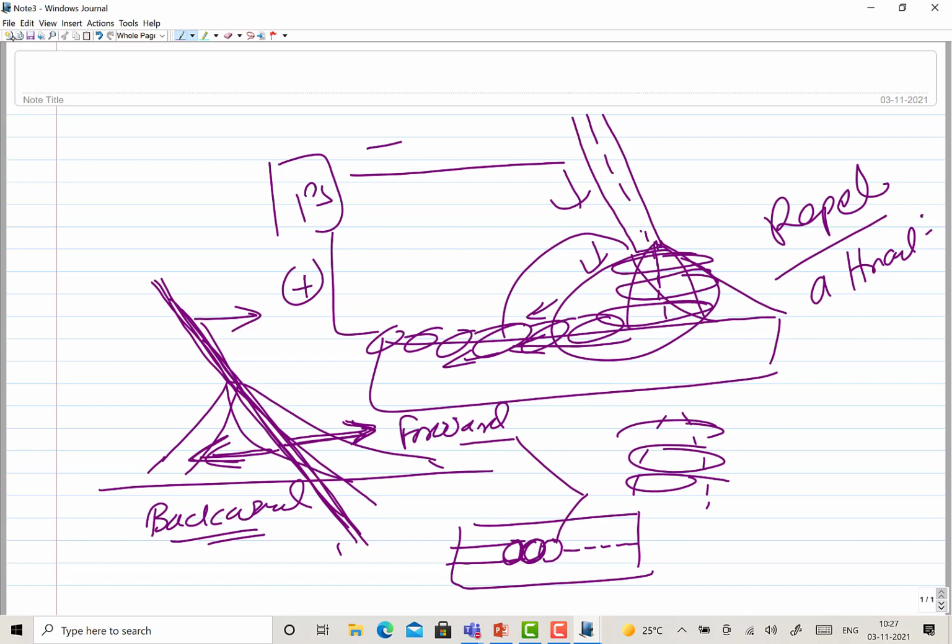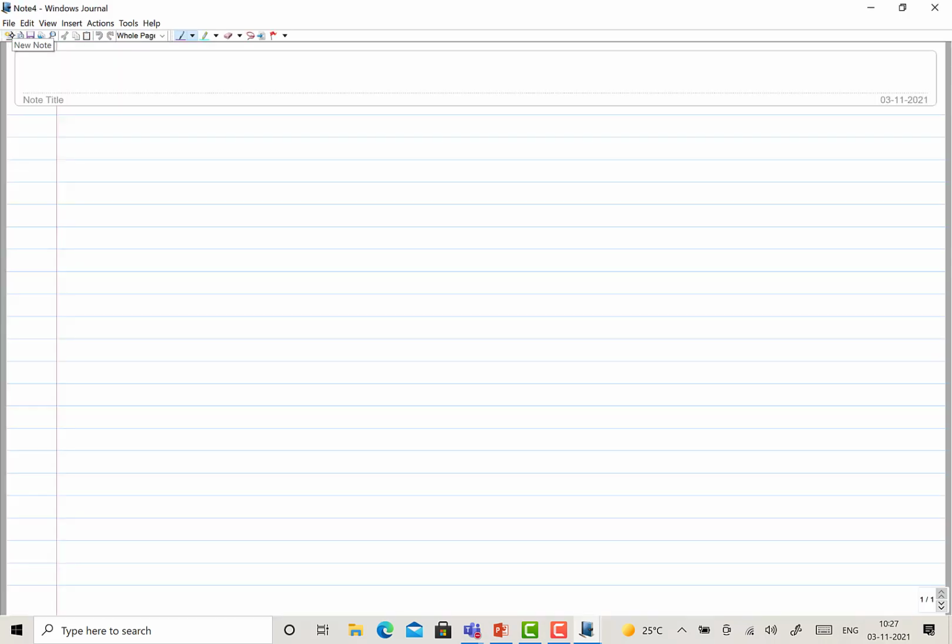The arc blow happens primarily due to the interaction of the electromagnetic fields generated by the flow of current through the arc and through the base metal. They can attract or repel depending upon the ground position, or the connection of the welding current.